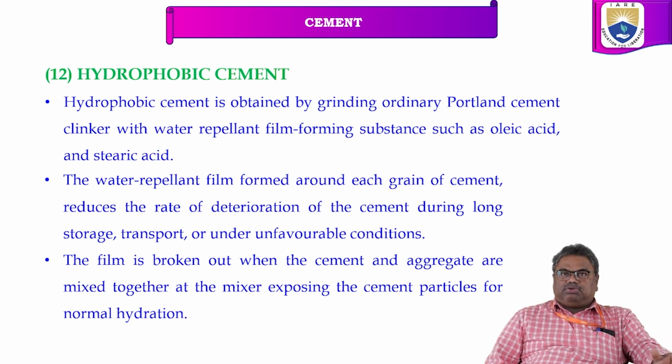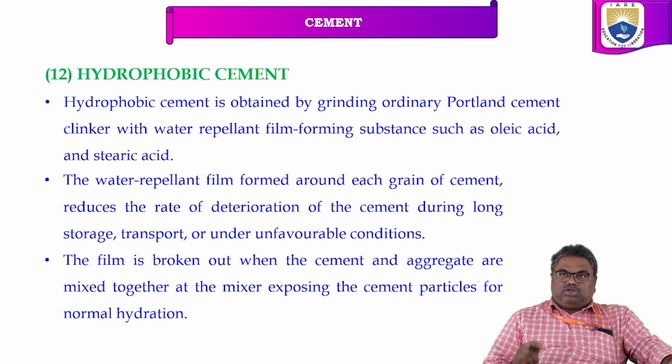Hydrophobia, you can tell from the name itself. So this cement will have a water repellent film around the grain of the cement. We are using acids, oleic acid and stearic acid, to form the water repellent film around the grains of the cement. Due to this, it will reduce the rate of deterioration of the cement during long storage and transport under unfavorable conditions also.